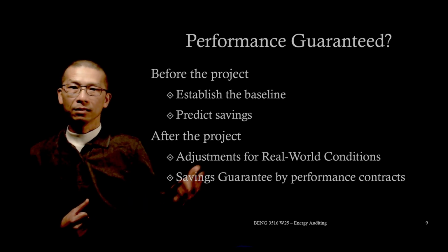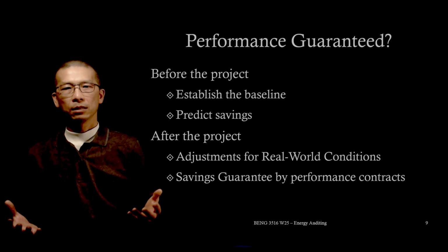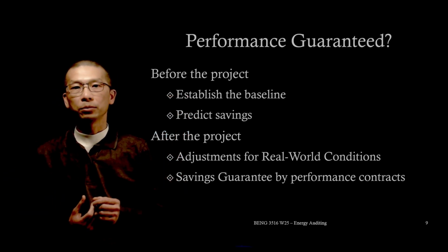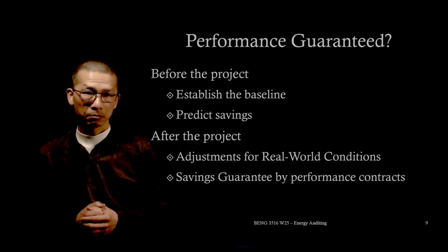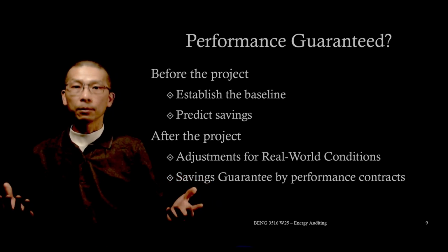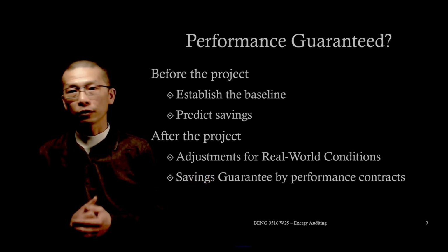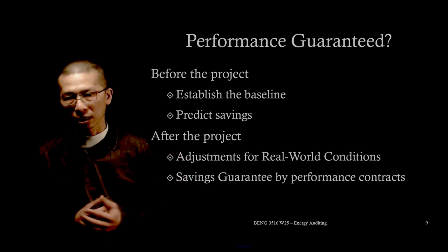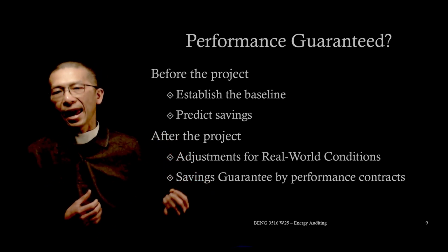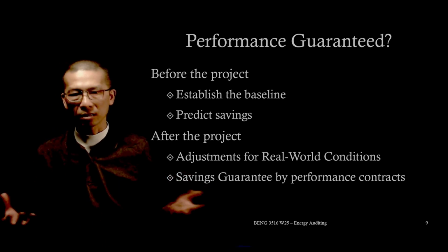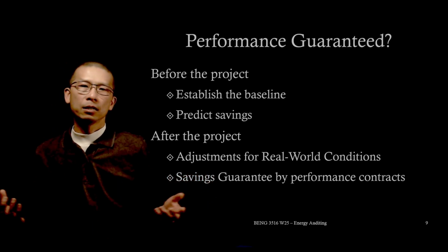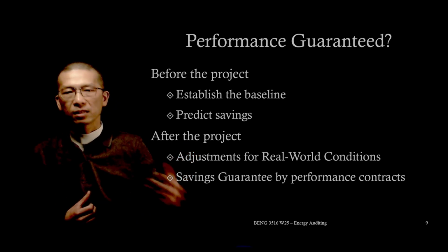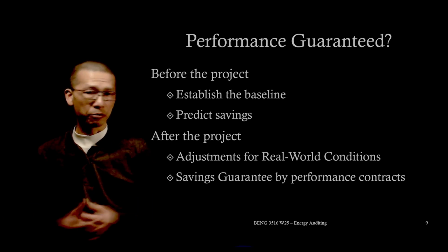Also, a lighting retrofit with LED fixtures has a manufacturer rated wattage. You can see how many watts per LED luminaire. Building automation upgrades as well reduce unnecessary HVAC runtimes based on more advanced control logic. Advanced energy modeling software like eQuest, EnergyPath, and EnergyPlus, or regression analysis, is often used to simulate energy savings under different scenarios.